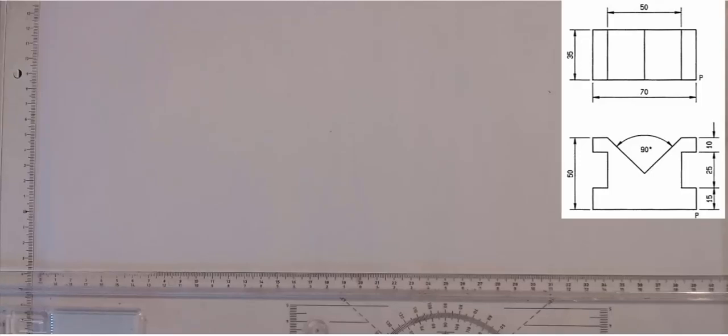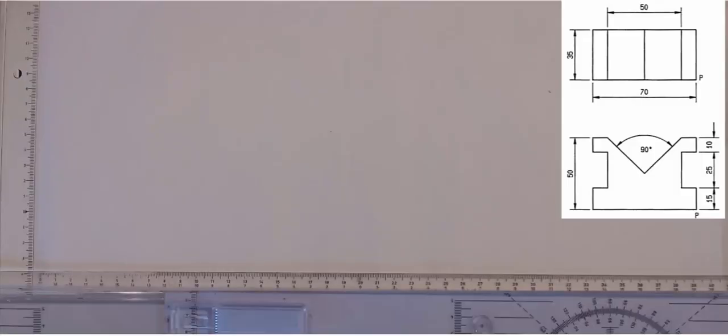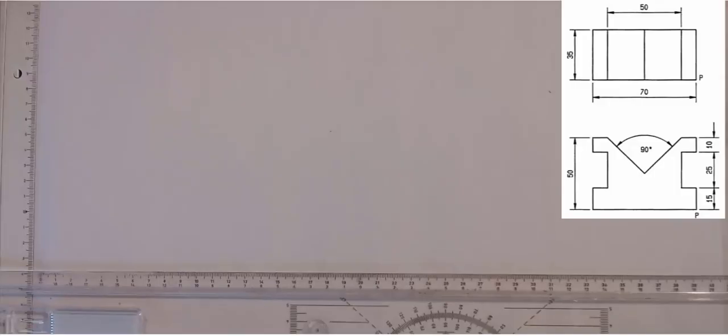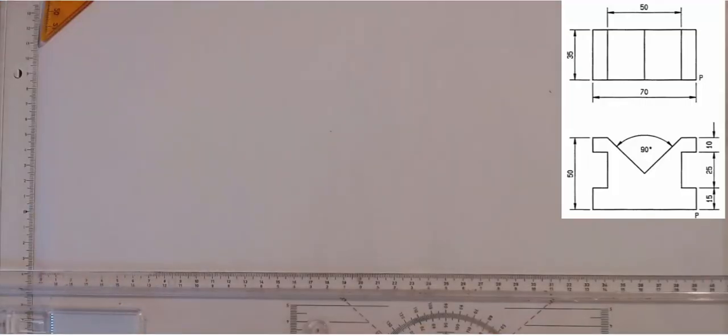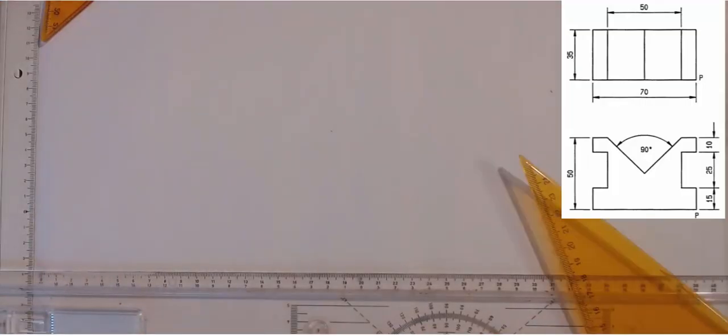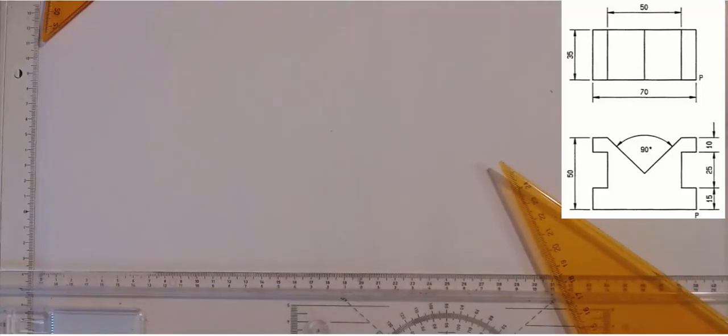Right, let's look at how to draw this example. So the first thing that we have to do is to make things balanced, right? We actually need to get the height from the PP, the picture plane, to the SP, so that we can plan out things properly. So here they give us 110 millimeters. So let's measure 110 millimeters.